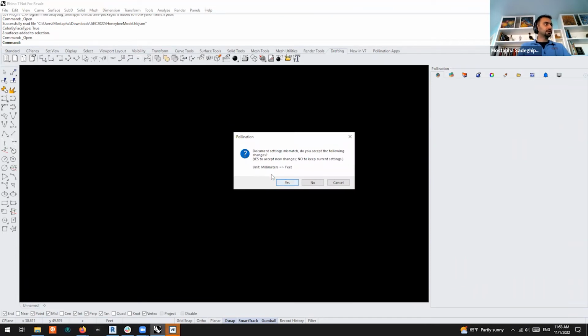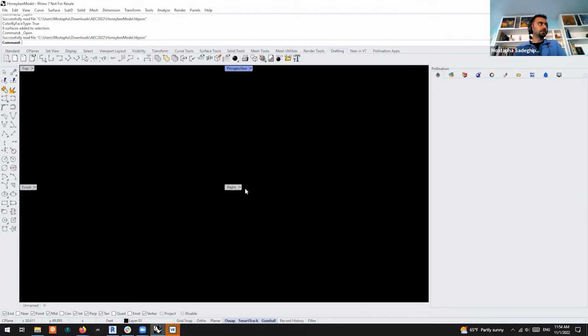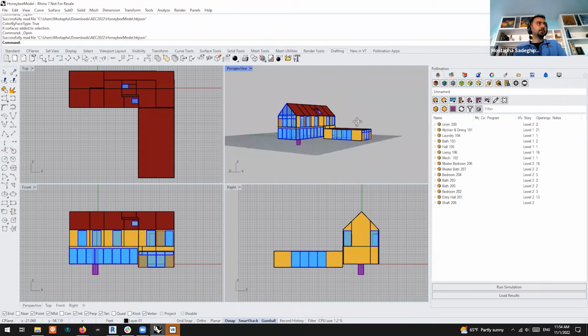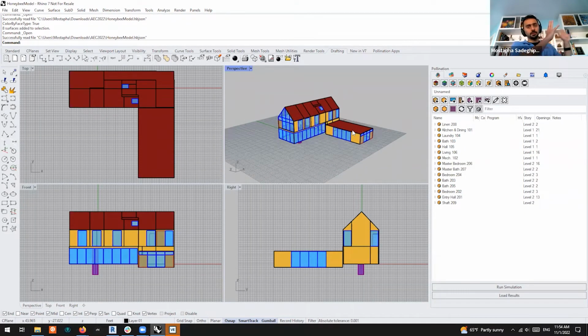It changes the unit. So one of the things that we have in Revit that we can do better in the future is we don't do the unit translation. So we just use Revit's base unit, which is feet. So every model that you export comes as feet when it goes to HV.json and comes to Rhino. You can change the units quickly in Rhino, but we can probably, or we should, do a better job and take your model units in Revit and export it like that.